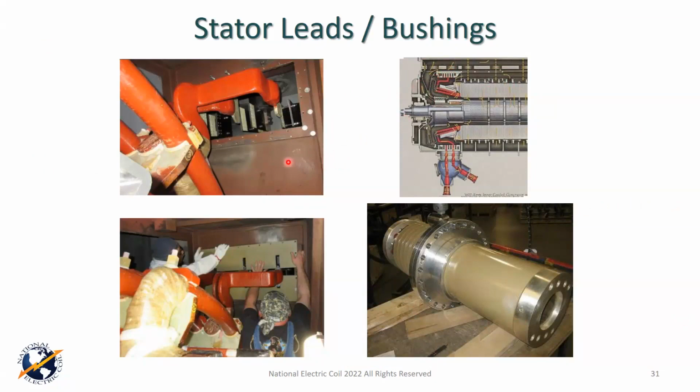So there's two ways we have to get that power through the generator frame. On air-cooled units and so on, it's no big deal. It's usually done with a bus connection. A lot of times there's flex links that go in, and I know there's a lot of things going on right now with the 501Fs and some of the Aeropack and even some of the modular main leads and flex links. But you have a penetration through the frame. There's usually a clamshell or boards that go down in here and allows that power to get out of the unit and into the isophase to go out to the GSU and on the grid.